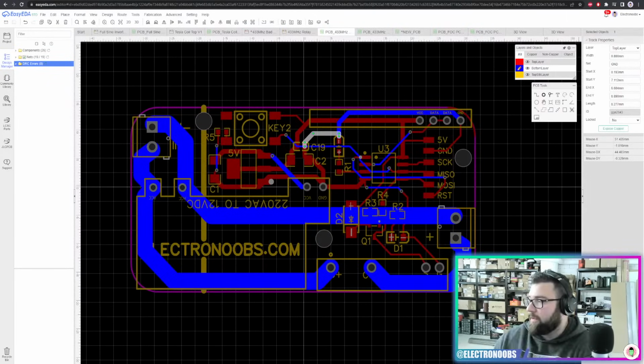Should we fill the rest of the PCB with copper? That depends on the project. I've just told you a few moments ago that, for example, if you're working with an antenna on top of your PCB, it's not that good sometimes to add a copper plane because that will create more noise or even create some sort of capacitor with the antenna.